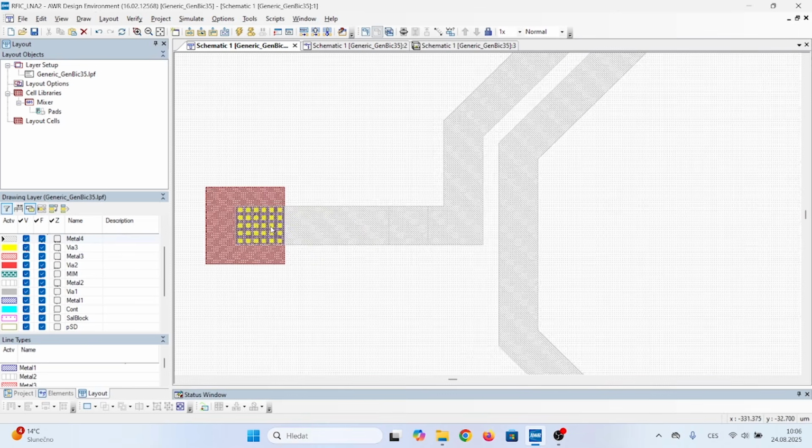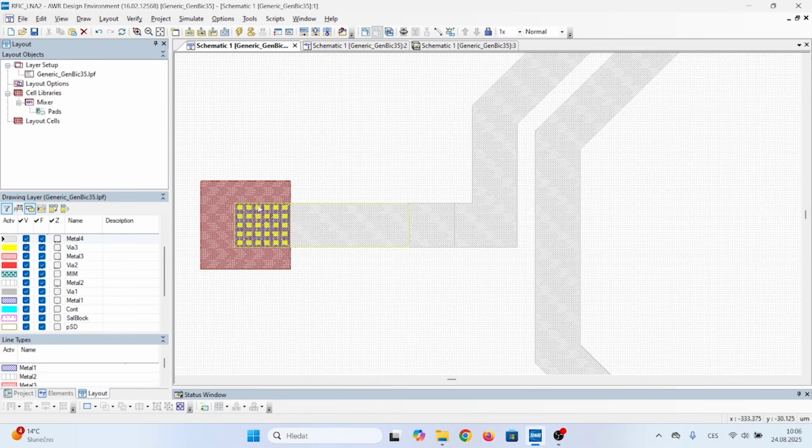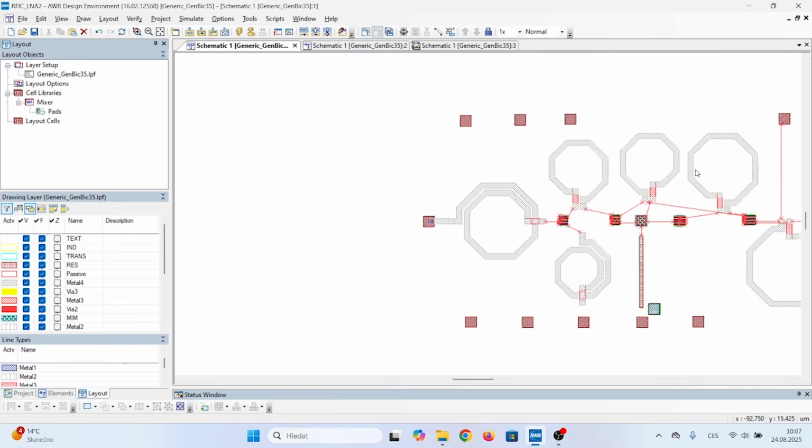Once we double click it, we can see it will create a device and connect the pin port, which is material poly, and it will create a connection to the metal inductor. We can see we work in metal 4 layers. In this menu, we will see all the layers we need. We will work with different metals for different connections. So this is really the simplest connection to our inductor.